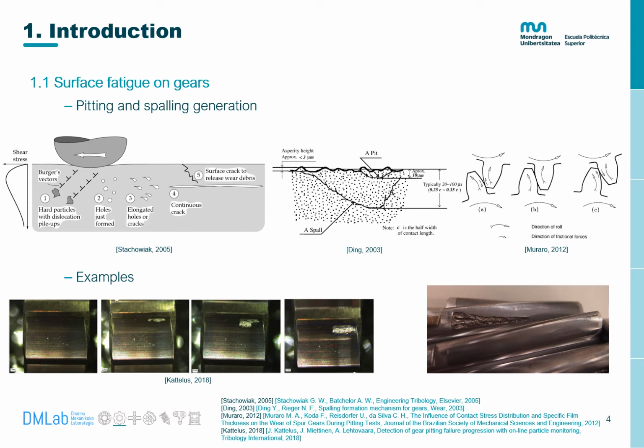These pits are the consequence of material fatigue resulting from a combination of contact pressure and surface sliding-induced shear stress. It is initiated when the local sliding and rolling contact stress exceed the permitted strength for the material. The failure due to the appearance of pits is known as pitting or spalling in the literature.